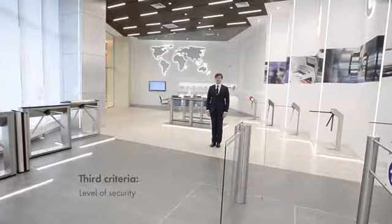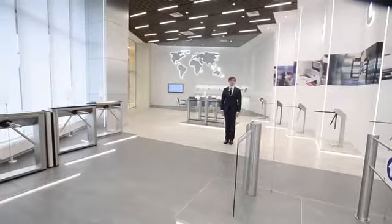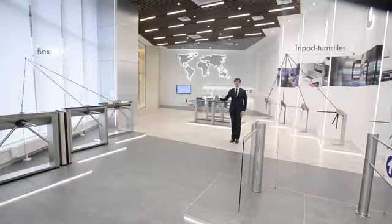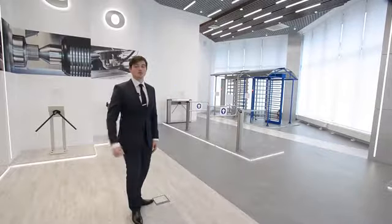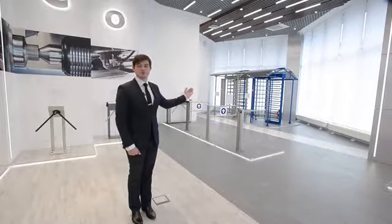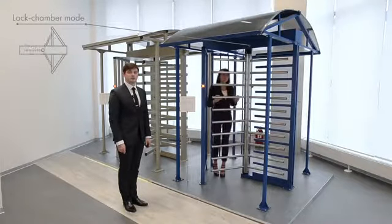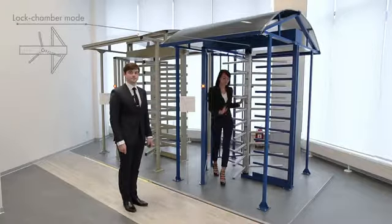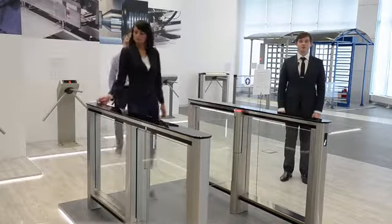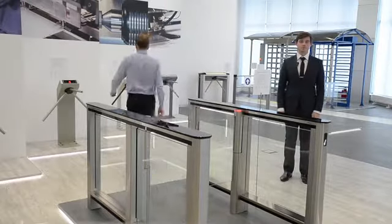Next selection criteria: providing correct level of security. In most cases, it is enough to install a waist-height turnstile. Tripods, box turnstiles, speed gates, but sensitive facilities require increased security. That can be achieved with full-height turnstiles. They not only fully block the passage, but can also work in lock chamber mode. Installation of a canopy will protect from climbing over the turnstile. All turnstiles must give access privileges for one person, not allowing passing one after another using one ID card.